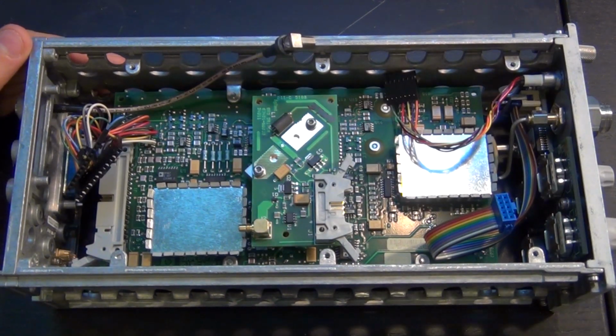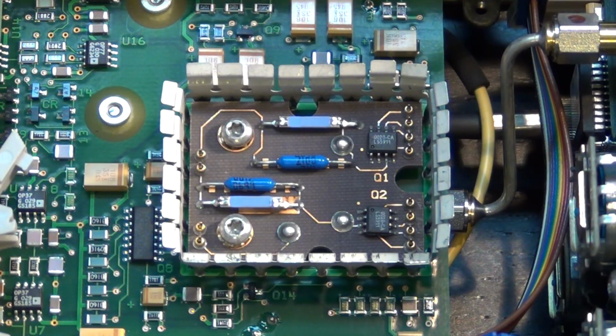And here's a close look at one of the IF modules, and we find underneath it exactly what we would expect. We have a pair of really ultra low noise JFET amplifiers, and this is exactly what these two components are, made by Linear Technology, and they have a noise of about 4 nanovolts per square root hertz at 10 kilohertz, which is pretty good.